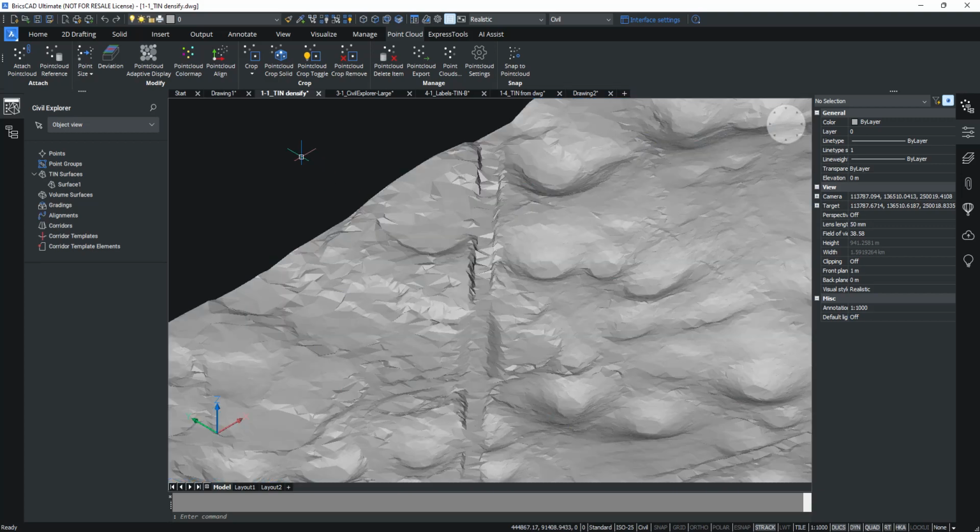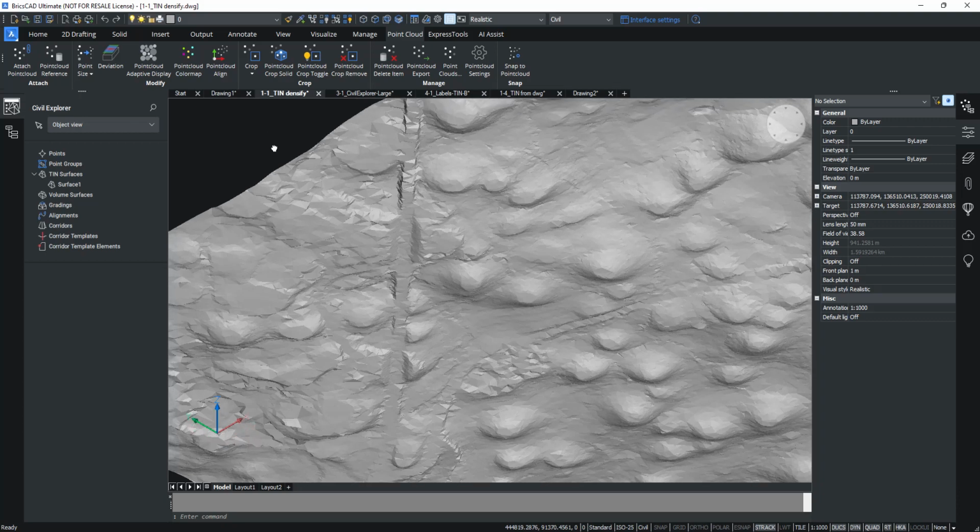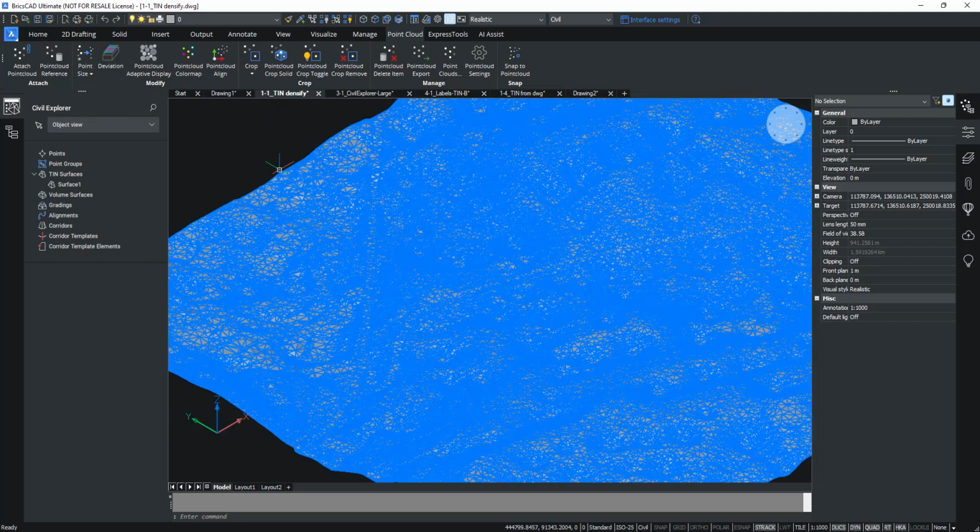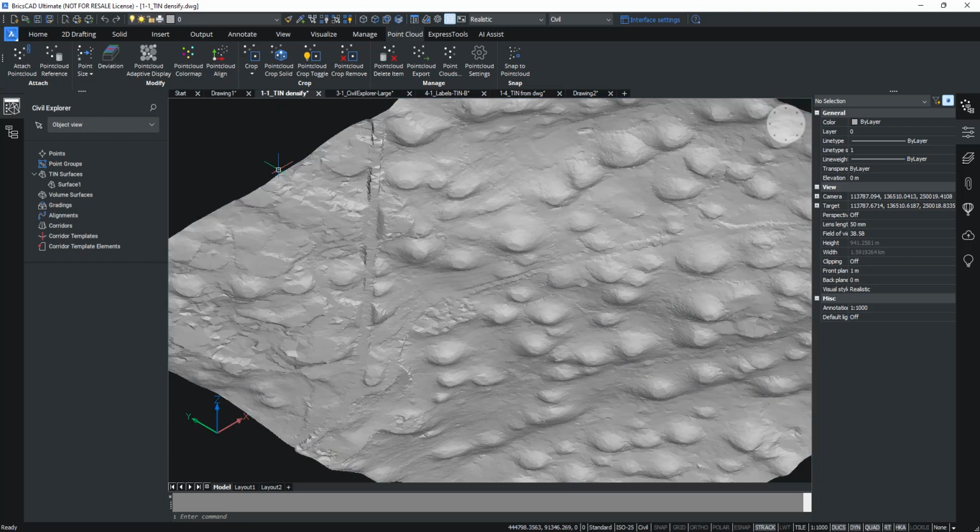Some of this does not look very tight for us, because when we simplified, the problem is that we told it to skip a bunch of points that were within a particular tolerance, but we didn't tell it which points to skip. So we can go back and densify this. If I pick my surface and go to definitions, just like we had before, you see it added points and removed outer edges for us automatically, and then created a snapshot for us.